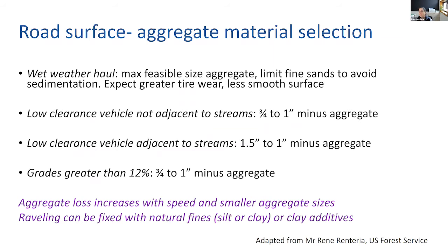For wet weather hauling, of course, we want the maximum feasible size aggregates and to limit the amount of fines in that aggregate to avoid sedimentation. Why do we want the biggest size aggregate possible? Because we want that water to drain out.